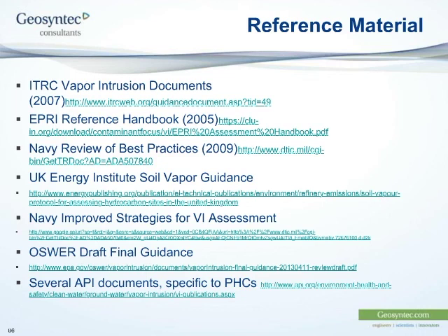So then Dawit said stratification is when there's continuous thin layers of soils. When there's discontinuous soil stratification, do you consider the relevancy of 2D or 3D numerical modeling of vapor intrusion? Well, this is where modeling sometimes breaks down. The models are often based on simplifying assumptions like uniform, homogeneous, isotropic, one-dimensional, or whatever. In the real world, those often don't apply.